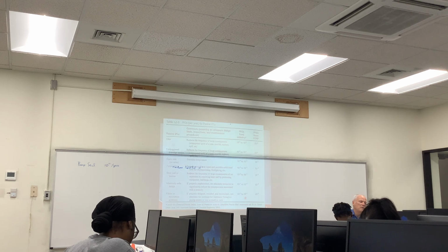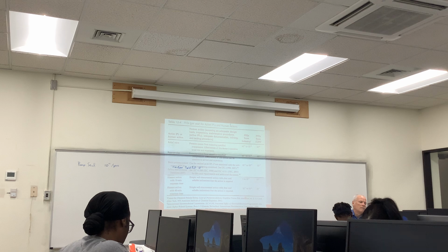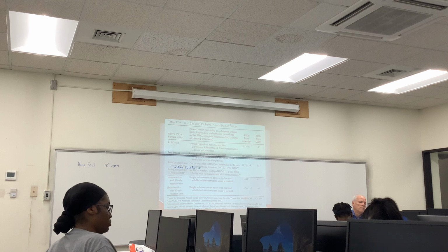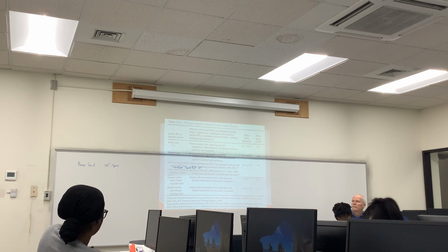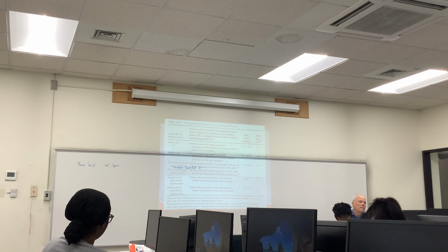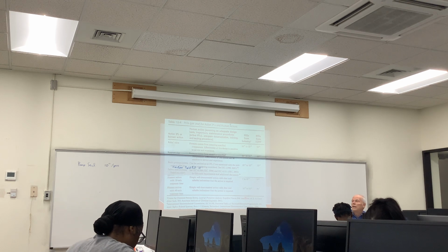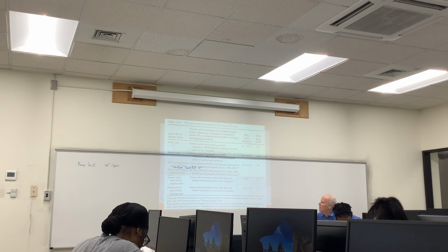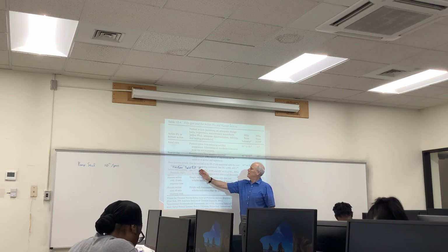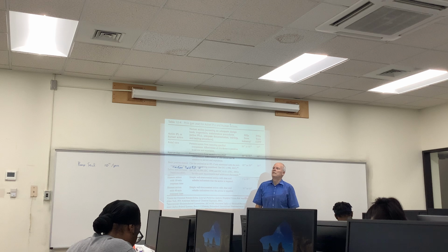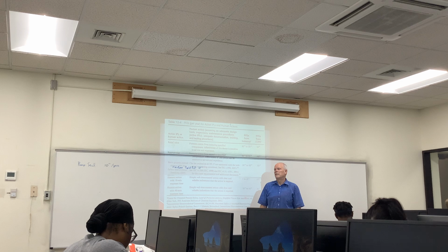So what are some examples of the IPLs that we might use? But it depends on where we said we got our fire. If the fire happened because the pump seal failed, then would a dike help? It might. I don't think they put dikes around pumps, do they?